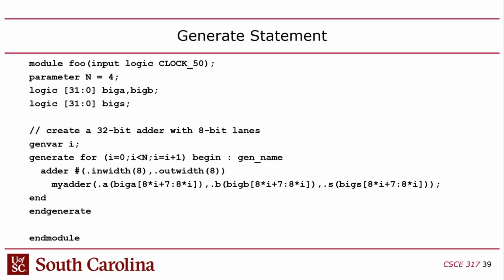Because you're going to write logic that does PWM, but you want to have a separate independent PWM generator for each light, right? You don't want them all, like in lab 2, where they're all going to be synced. The lights get brighter, dimmer, brighter, dimmer, brighter, dimmer. But in lab 3, we're introducing this thing where we want them to all be independent. They should all have independent PWM values. So in order to make that work in Verilog, you would then just generate a PWM module for each one of the 26 lights. Now the syntax here again is kind of weird. I always have to look this up.